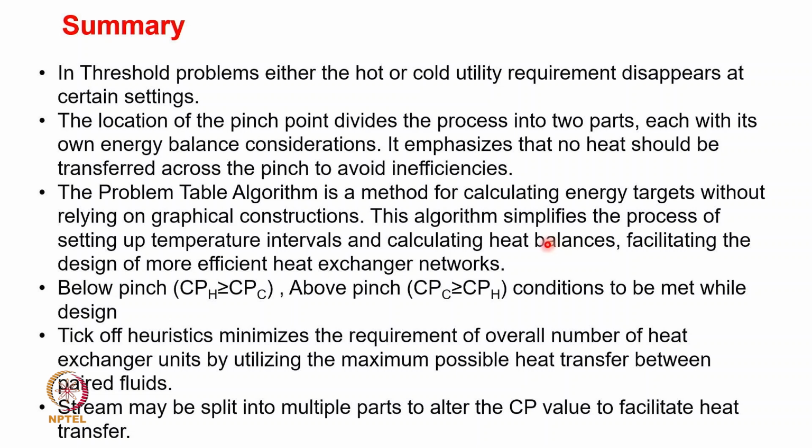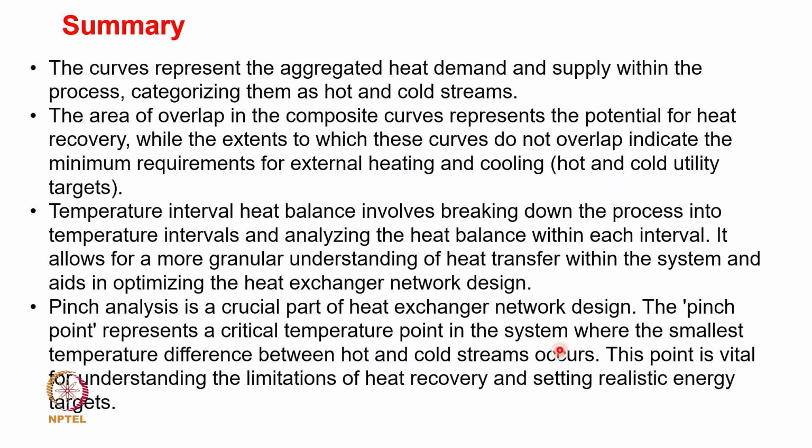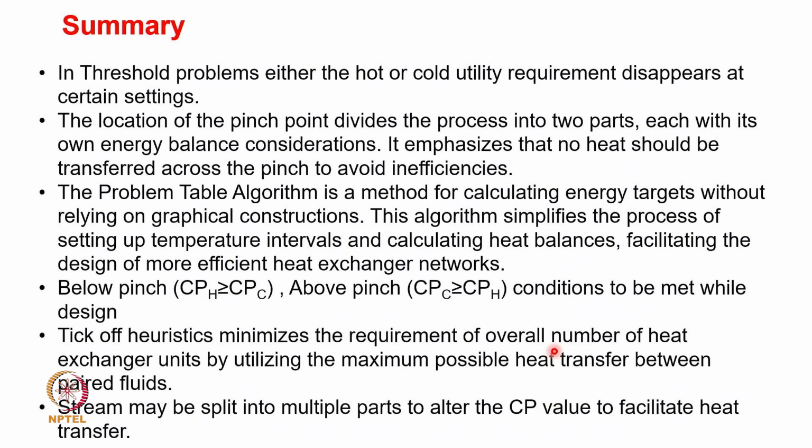The problem table methodology that we have learned here helps in calculating the energy targets without relying on graphical constructions. The algorithm simplifies the process by setting up temperature intervals and calculating the heat balances, facilitating the design of more efficient heat exchanger networks. The below pinch and above pinch conditions, the CP conditions, have to be met while designing. And lastly, we have to use tick-off heuristics that minimize the overall number of heat exchanger units by utilizing the maximum possible heat transfer between the paired fluids. A stream may be split into multiple parts to alter the CP value to facilitate the heat transfer.